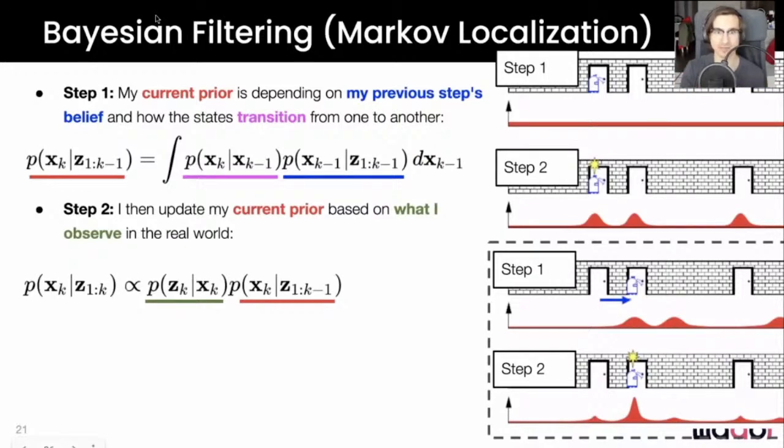On the right, we see an illustration of a Bayesian filtering procedure. The state space here is unidimensional. It's just a scalar that depicts the robot's position in a corridor. So it's just one number. And the robot at the top begins with basically no idea of where it is. The belief over the state space therefore corresponds to a uniform distribution. And in this case, since we are thinking about the entire state space, this is a form of a simplified global localization, since the robot basically doesn't start with any prior knowledge on where it could be in the environment.